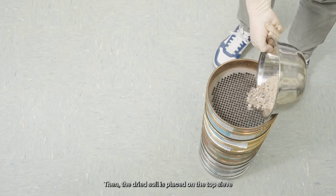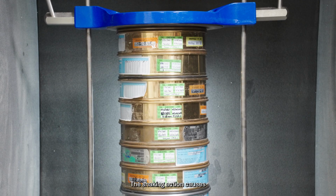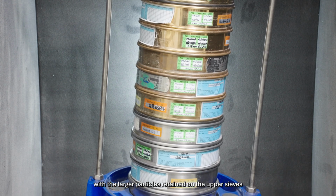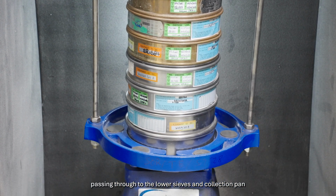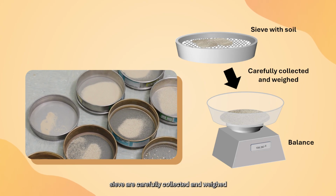Then the dried soil is placed on the top sieve, and the sieves are mechanically shaken in a controlled manner. The shaking action causes the particles to be separated based on the size, with the larger particles retained on the upper sieves and the finer particles passing through to the lower sieves and collection pan. After sieving, the retained particles on each sieve are carefully collected and weighed.